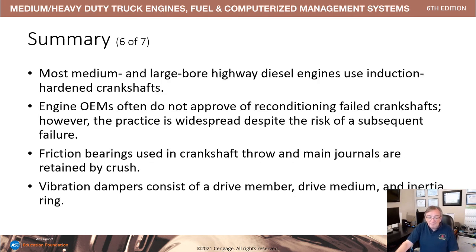We have essentially induction hardened crankshafts. That's where the electrical component comes down to the crankshaft, puts a certain amount of AC voltage and a certain period of time into that area between the two assemblies that drop down, and they will put enough heat into the component to allow it to have the correct temper.